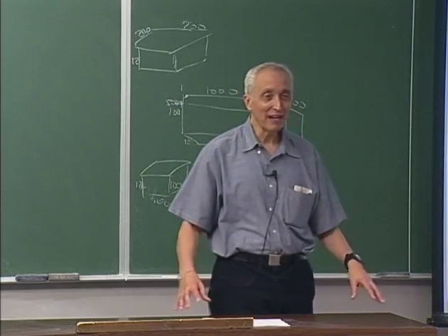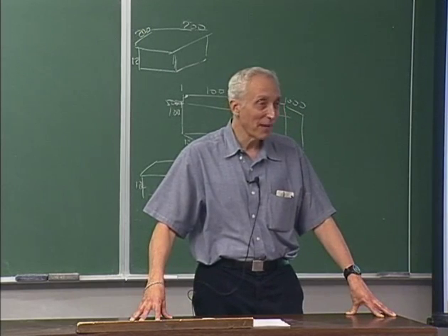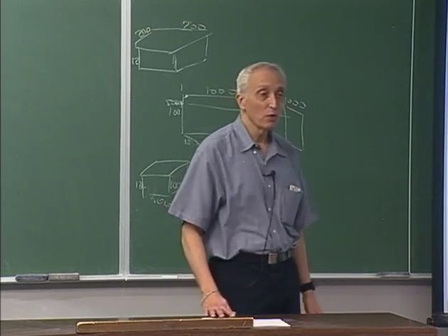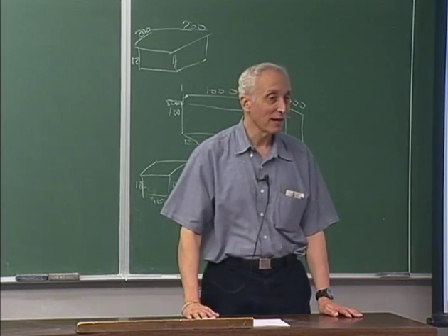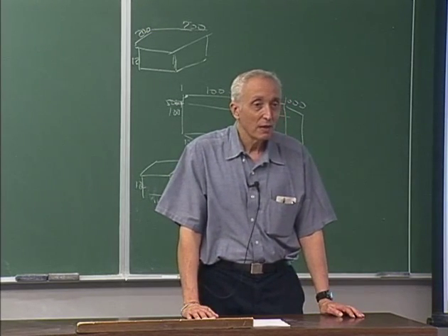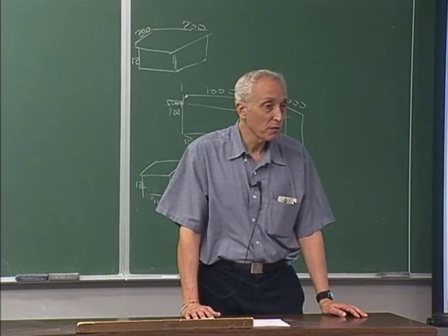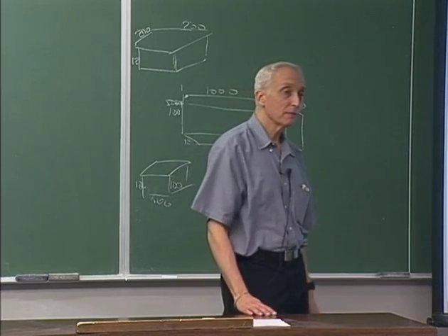In general, the front seat is much more utilized than the back seat. So if you are to suffer a vibration mode, you don't want the peak amplitude to be at the driver's seat. And there are maybe other places where it's also sensitive. So mode shaping is important.